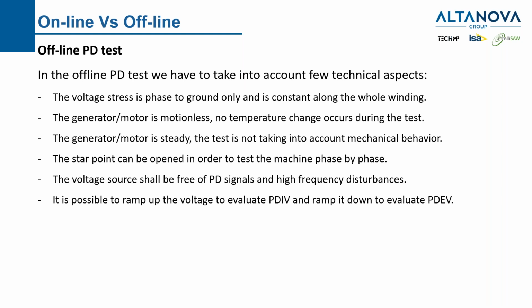One very practical aspect is that we can ramp the voltage stress up and down in order to evaluate the PD inception voltage and PD extinction voltage, very classical parameters normally used during laboratory testing.